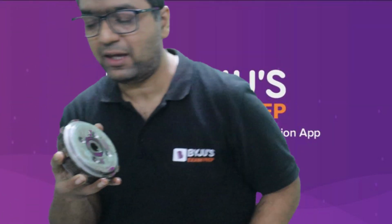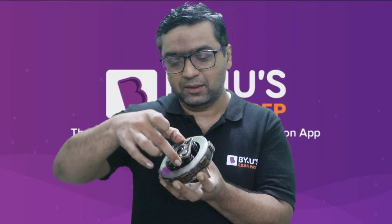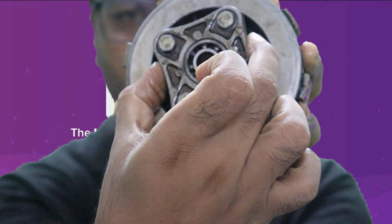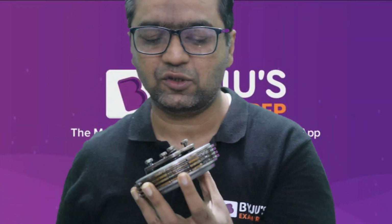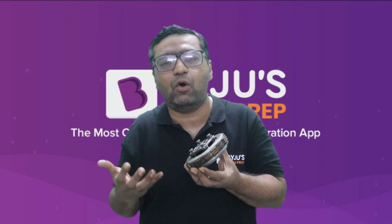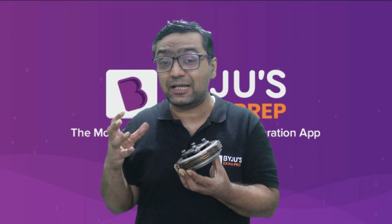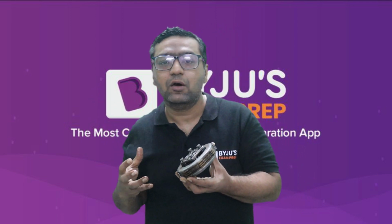So guys, now we are going to look at this. Major discussion will be on this. Here if you can feel, there is a plate, and there are 4 springs. If you want to see, yes, I am showing you. There are 4 springs, and because of the springs in compression, the always-engaged condition is there. You only need to disengage the clutches. They are always in engaged position because the majority of the time we want engagement. We want engine power to be transmitted to the transmission and to the wheels and all.